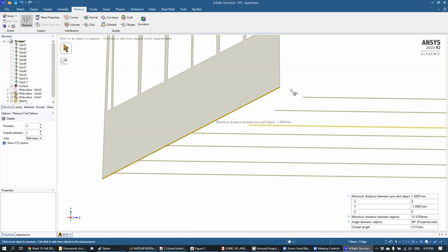All right, so the question is, it looks like the beam also needs to move in the X direction, but the X was 0 before. Yeah, that's a good question. For the X direction, we allowed the extend tool to handle that. You're right, the beam did need to be extended in the X direction, or I guess in this case the Z direction, in order to meet the plane here. But we let the extend tool do that because we're actually extending the length of this beam to meet this structure right here. That's usually better handled by the extend tool. The only thing we did was make sure that the two are in line with each other, so that when they extend, they actually intersect.